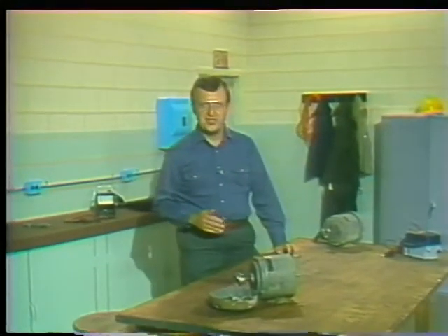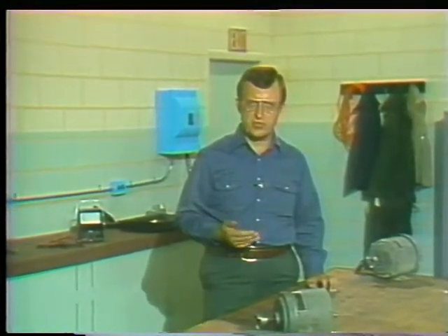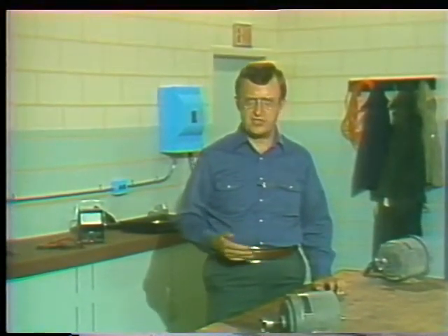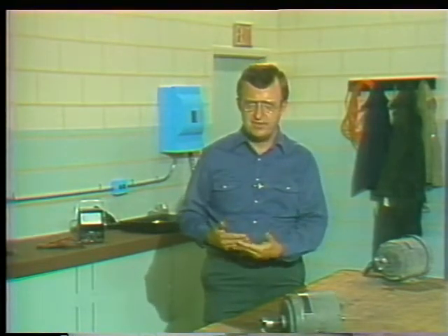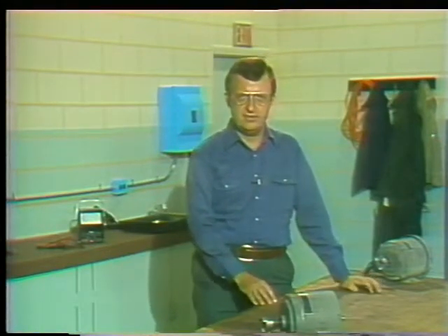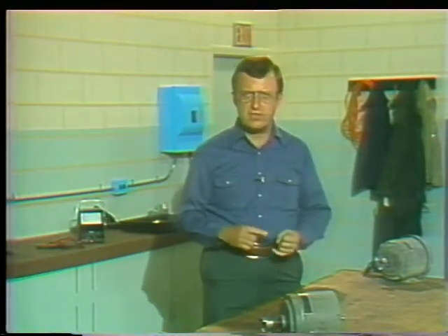Well, you've seen how the rotating magnetic field of the stator causes the rotor to turn. You should understand that rotor speed is determined by the speed of this rotating stator field. The difference between the speed of the rotor and the speed of the stator's magnetic field is known as slip. We've discussed how a change in slip affects how strongly the rotor turns. We've looked at two common types of rotors, the squirrel cage and the wound rotor.